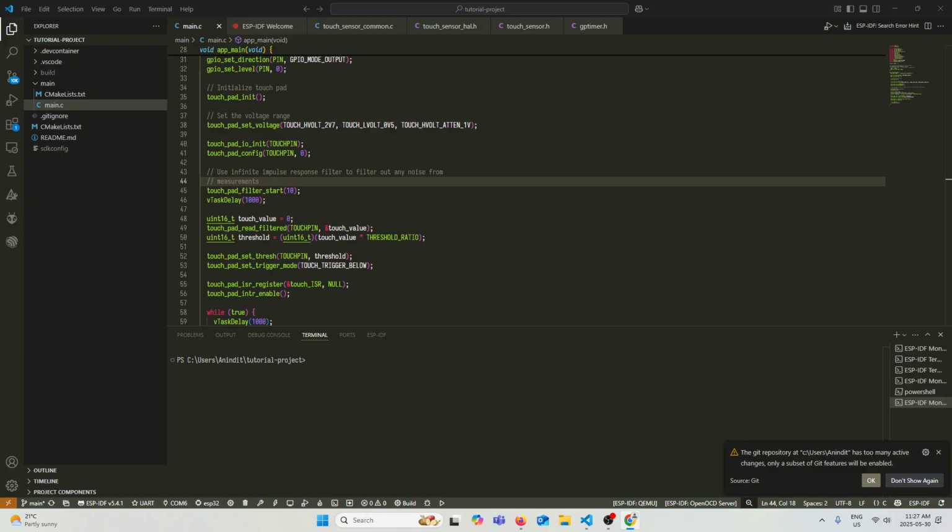Furthermore, we can also use a calibration driver to get more accurate results. As I've said before, different ESP32 chips may have different reference voltages, and thus setting up calibration can minimize the effect of this behavior.